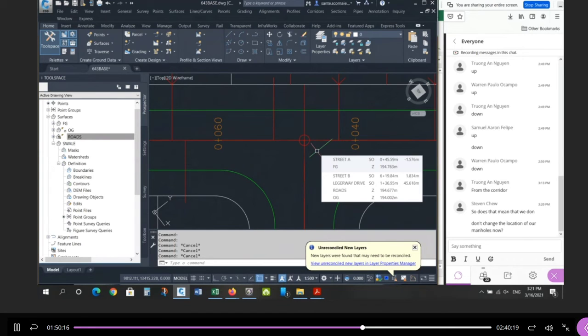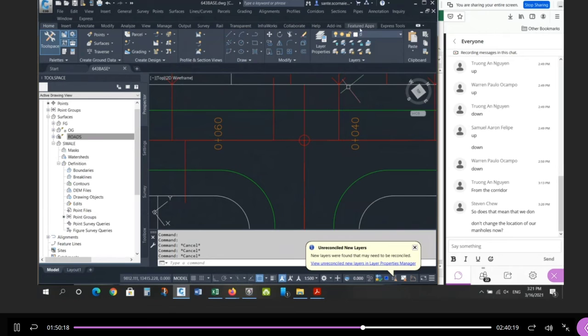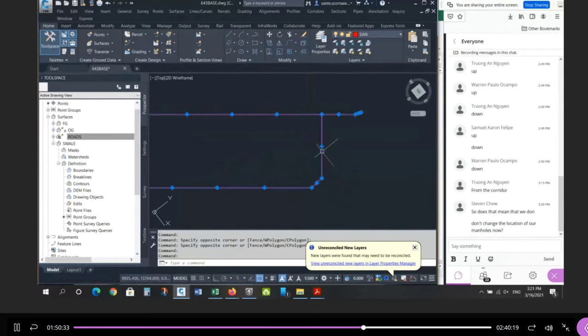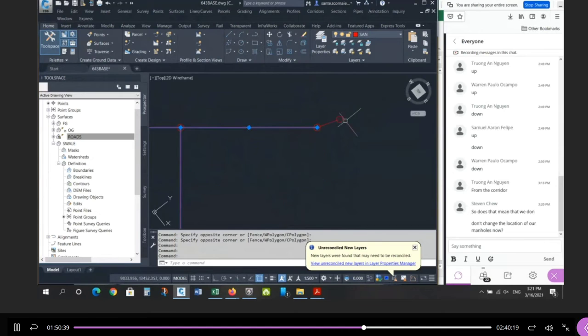Okay? I think they're pretty good for the layout you have. If it's similar to what I've shown you, it should be good enough to design, right? You should have 1, 2, 3, and maybe a short little pipe here. Existing, don't forget the existing. And then you should have 2 here, a short pipe here, and then 1 more here. So generally you should have 1, 2, 3, 4, 5, 6, 7, 8, plus the first existing pipe, 9 lines on your spreadsheet.